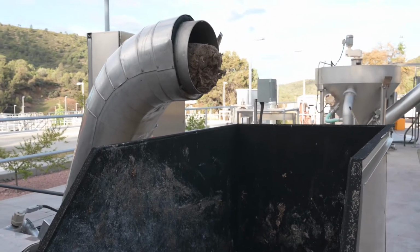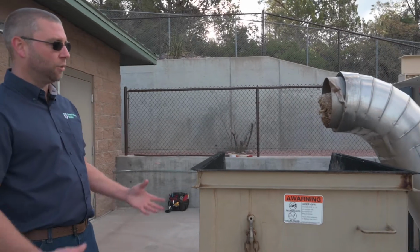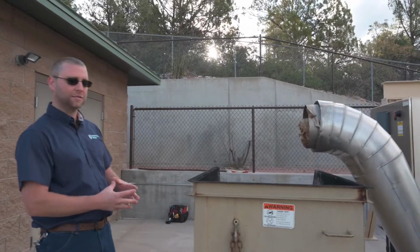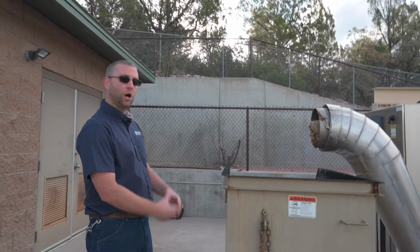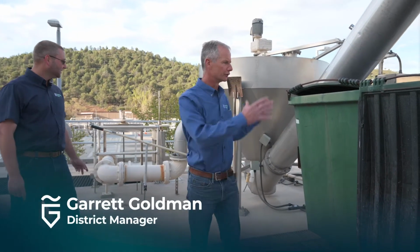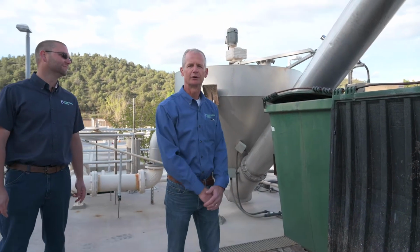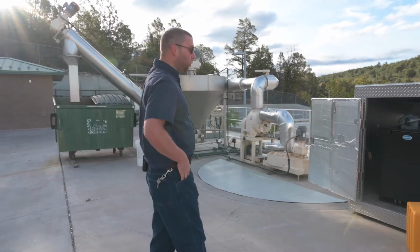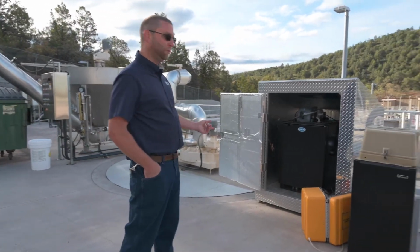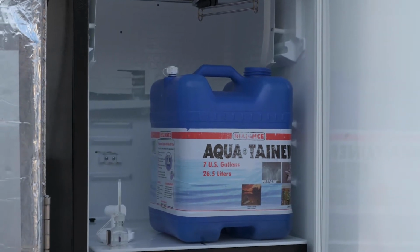So after the step screen removes the rags, it goes into our compactor. The compactor will help clean all the solids off the rags and compress it and help squeeze the water out. And then it flows down here into our grit removal system, and then from there it goes into the treatment process. So after we go through all the headworks process, we have a sampler that runs twice a week, and that is so we can send down samples for compliance.